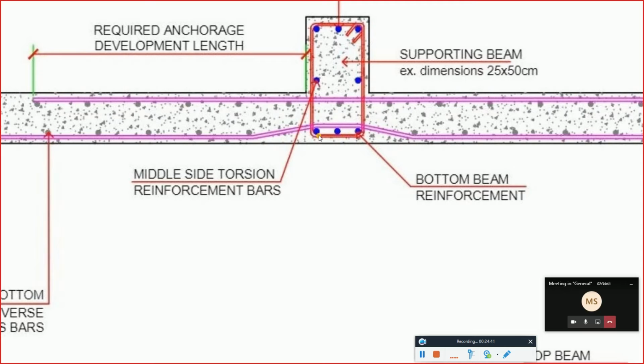In regular beams, the slab is carried by the beam. In hidden beams, the slab is carried by the beam. In inverted beams, the slabs are carried by the beam. So in all scenarios here, the slab is still carried by the beam. The load of the slab is going to the beam. The only thing is that instead of keeping it down, we are keeping it up, exactly the same design. I don't need it at the bottom, I need it at the top.